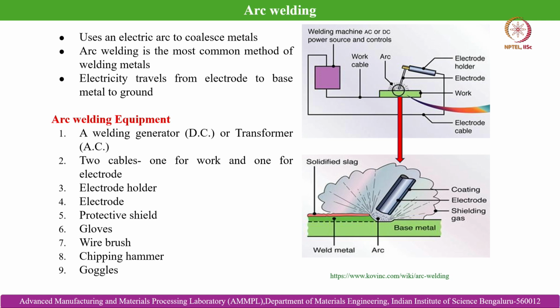The only difference is that in case of TIG, if it is not autogenous, then we have to provide the filler material separately, that means it is not clubbed with the welding torch. Whereas in case of metal inert gas welding, it is the electrode which is consumable in nature, which gets deposited for joint preparation and that is fed through the torch.